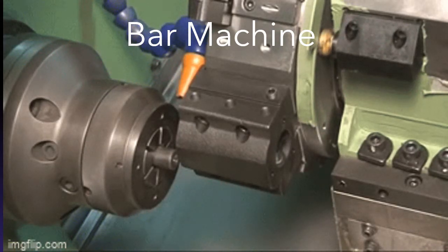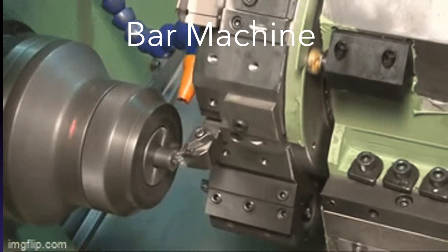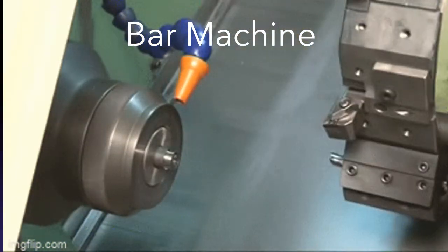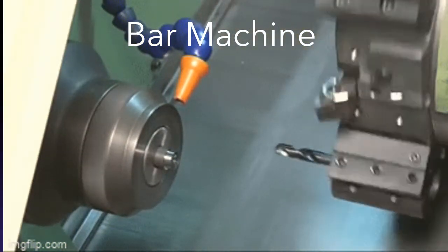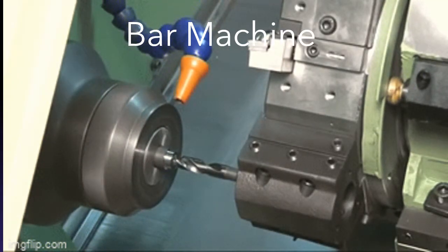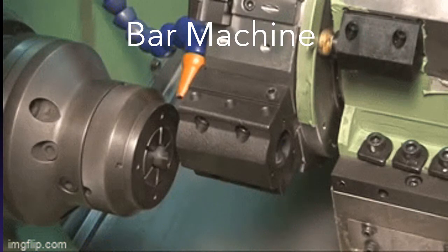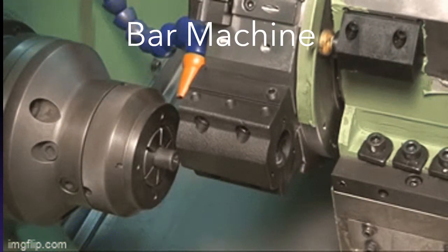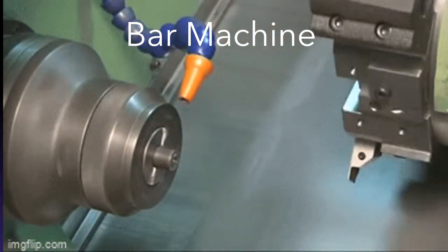The bar machine is similar to the chucking machine except that a collet is used instead of the chuck, which permits a long bar stock to be fed through the headstock into position. At the end of each machining cycle, a cut-off operation separates the new part, and the bar stock is then indexed forward to present stock for the next part.